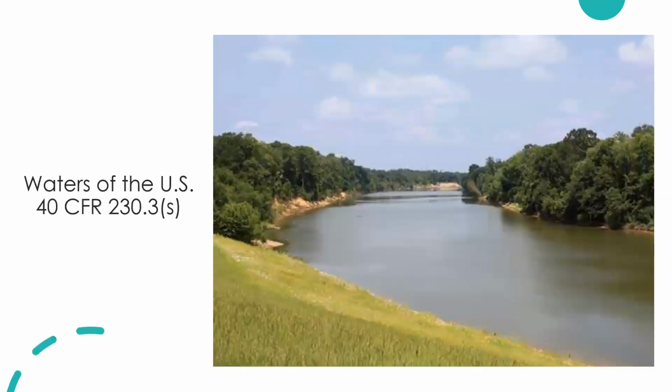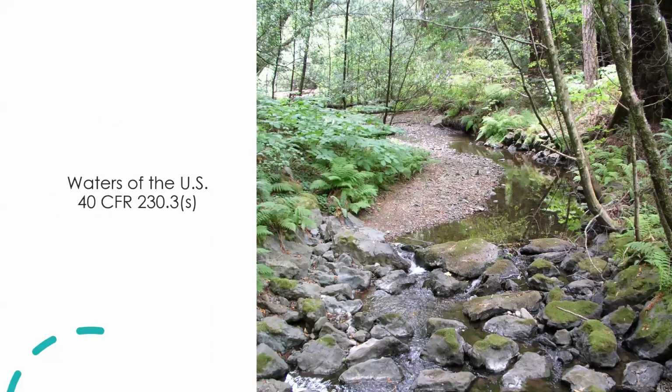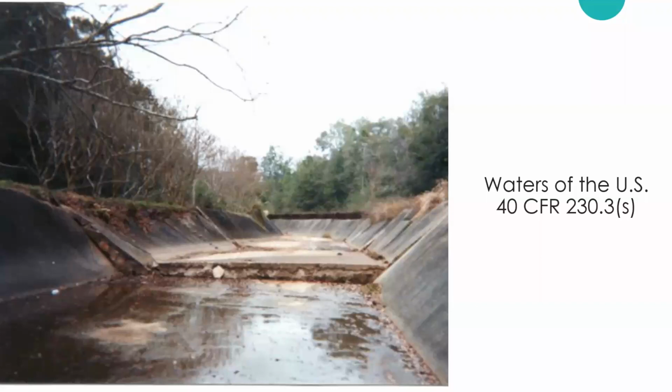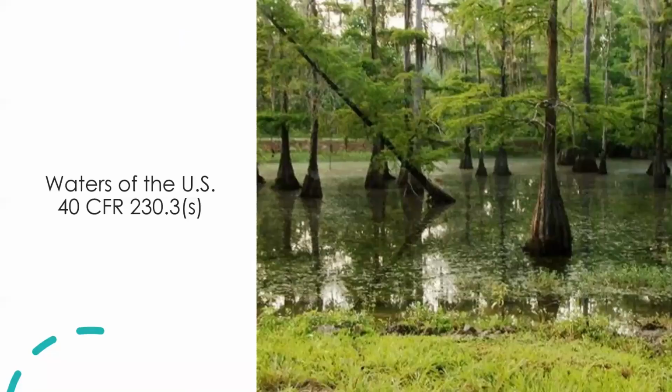Some examples of this, rivers are going to obviously be one. We've got barges traveling through here, commerce is going on actively, but one you might not think of is just your simple creeks right outside your facilities. These are tributaries to these bigger streams. So if we've got pollutants here, they're eventually going to end up in the bigger waterways. This is true even if they are cement lined. So cement lined conveyances are still considered a water of the US, as well as our wetlands.